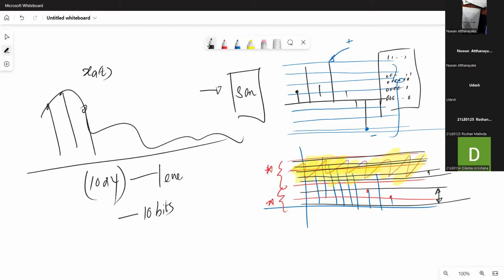But if you really want to reconstruct it, as we discussed during the previous session, whatever sampling frequency you select should not have this aliasing effect. If you select a proper sampling frequency without aliasing, you can reconstruct the original signal. So the sampling frequency is the one you select at a sampler, but the Nyquist rate is a property coming from the continuous time signal. You can see this difference once it is described in the answer to the next question.